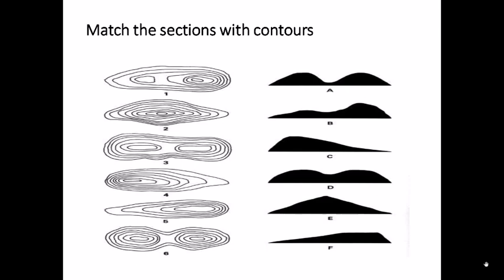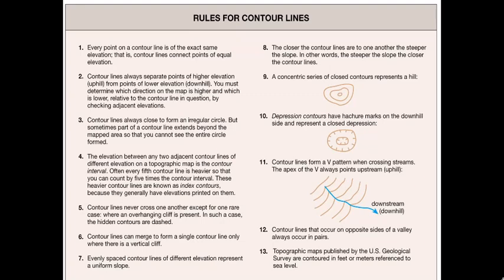If you see over here on this map 5, that pretty much goes along with it. You have on this side a flatter surface, that's why a bigger loop, and the slope is steeper over here. So the contour lines are very close on this side, and the slope is very mild over here. That is why the distance between the contour lines is bigger on this side. So this is how you get a picture by looking at these maps of what sort of land we are talking about. You can do the rest of them and follow the same principles.